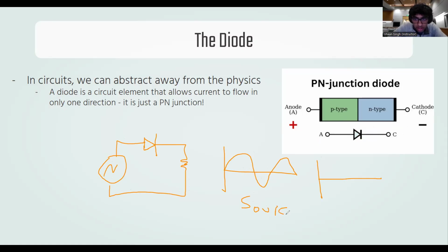it's called a rectifier. Instead of delivering the negative part, I'm just going to deliver this, right? Because only the positive part gets through. Okay? And that's important for devices that can't have voltage flowing in the wrong direction, otherwise you'll break the device. For example, a lot of ICs, integrated chips on circuits, can be damaged by having strong negative voltage applied to them. A rectifier is an important part of converting AC to DC.